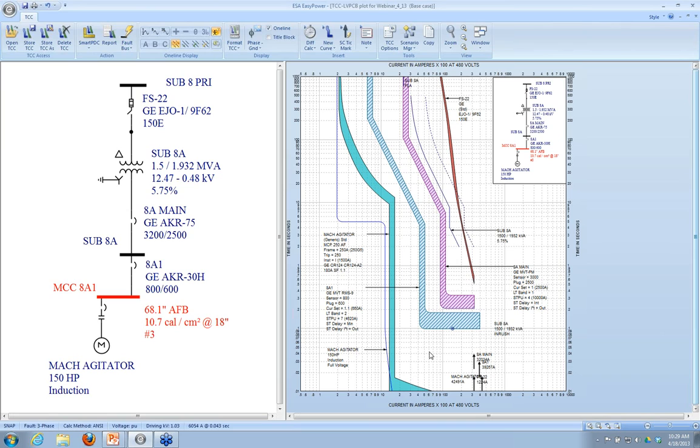The other thing in arc flash now is that the newer breakers will have, even if they don't have an instantaneous function for their normal protection, a maintenance mode. So you can switch in the instantaneous. Like we just did there, if someone is doing work on that motor control center, we switch into maintenance mode, turn on that instantaneous, and it will reduce the arc flash. You know, we take the risk of not coordinating during maintenance to protect the workers.